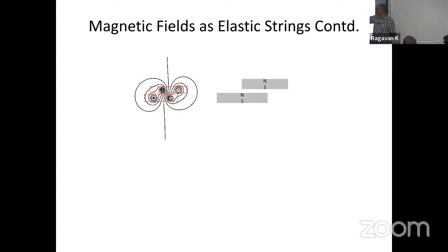It's like the bottom coil is one north-south magnet, and the top coil is another north-south magnet. If you see the resultant fields, the magnets want to slide into each other, right? If you don't let them slide and just keep moving, then that force is maintained. This is what happens inside machines. You maintain orthogonal, electrical 90 degrees between the stator field and the rotor field, and you keep rotating the stator field to get the torque. There are different versions of implementing it, and we have different classes of machines, but essentially these kinds of fields and their stresses create torque inside the machine.